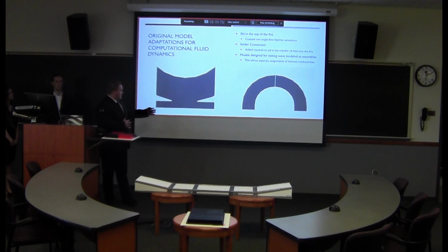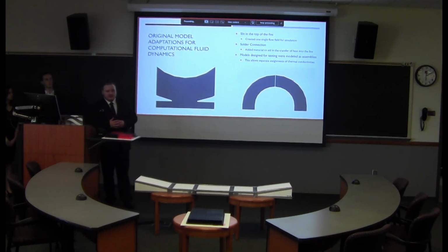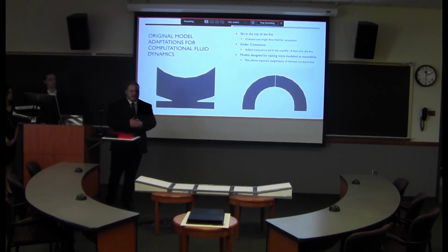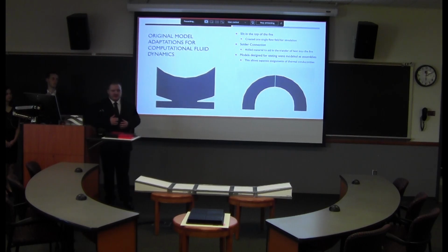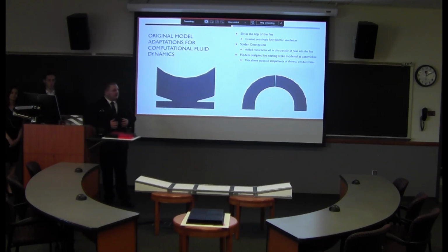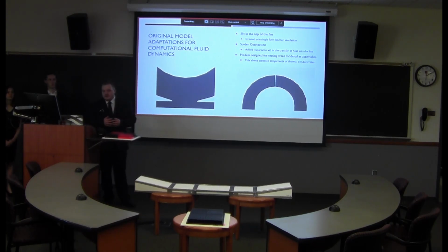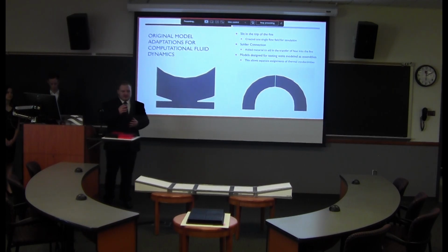On the left, you can see there's some added material underneath of each fin. That is to simulate a spec'd solder connection at the bottom of each of them. This allows for heat to be transferred from the base into the fins, as well as providing a little bit of structural support. Finally, all of these models had to be modeled as assemblies. This is due to BPMI telling us that the fins and the base plate have different thermal conductivities. Modeling all of these as assemblies, we're able to help accomplish that.